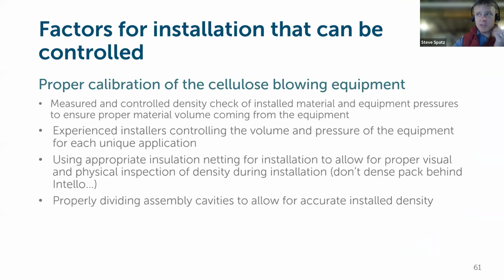time. Similarly, spray foam could not be installed against a dry substrate or under certain conditions where the foam could shrink back from the substrate that it was applied to as well. You don't want those sorts of occurrences happening, and you don't want those gaps opening up. That creates some very vulnerable pockets within the assembly that can fail over time. But getting back to cellulose specifically, calibration of the equipment being used and the installer who's using that equipment really has a huge impact on long-term outcome and durability.